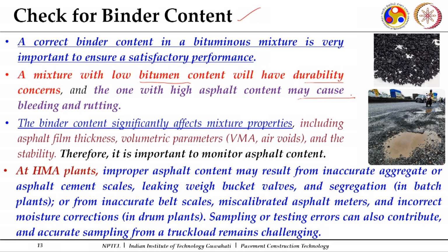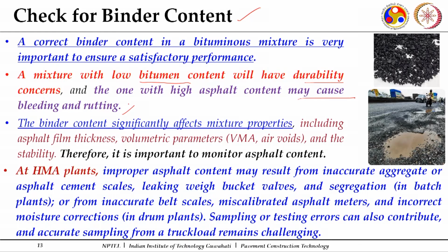So, if the binder content is inadequate, there will be concerns related to durability, and if the binder content is in excess, it may result in challenges associated with rutting, where deformation occurs, and bleeding, when the binder comes over the top. These kinds of concerns may arise if the binder content is more than what is designed.